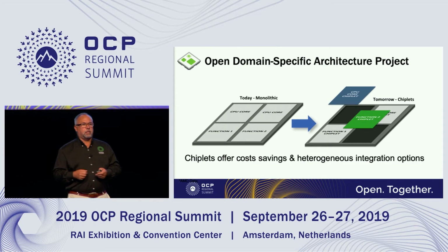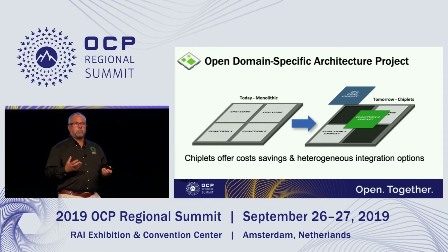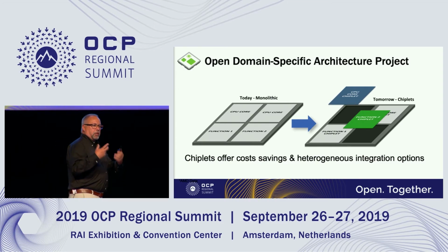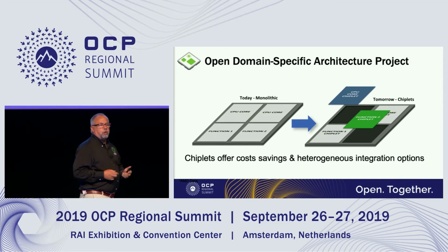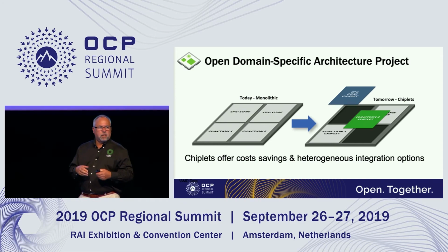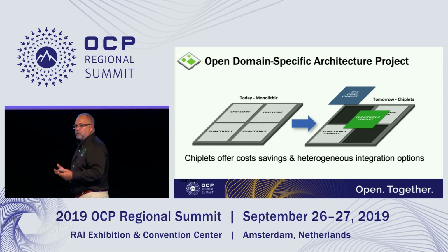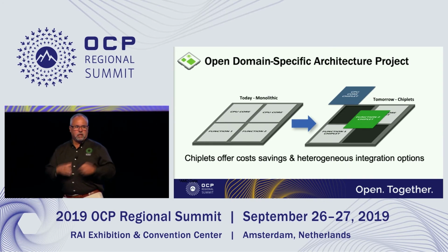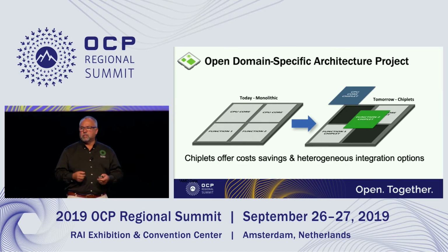There's also an opportunity to take different die from different suppliers that are very good at a specific function. Maybe it's an FPGA function, maybe it's a special network processor function, or a service processor function. It may have another die that handles memory management, yet another one that could handle I/O functions. And by taking the best-in-class die and putting those together, we get potentially breakthrough performance if we can put all of that onto a single SoC.